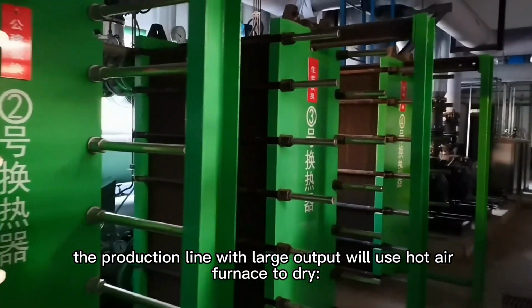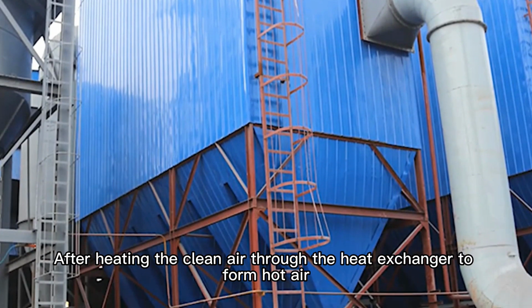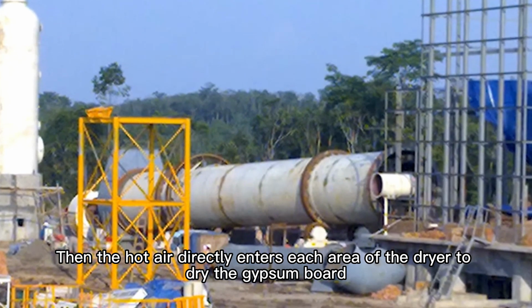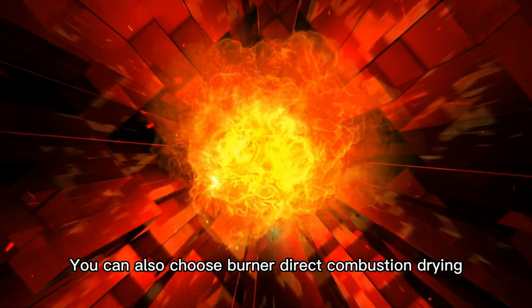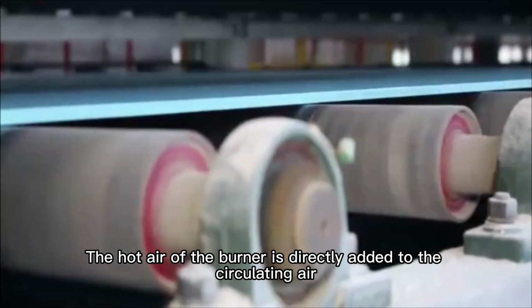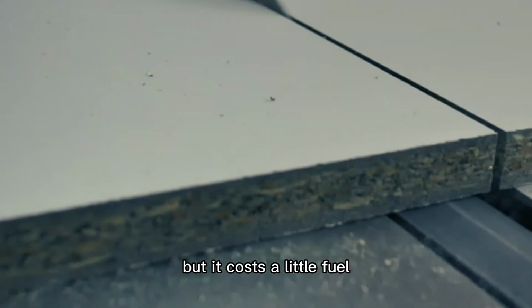At present, the production line with large output will use a hot air furnace to dry. After heating the clean air through the heat exchanger to form hot air, the hot air directly enters each area of the dryer to dry the gypsum board, which is clean and hygienic. You can also choose burner direct combustion drying. This is a new drying method. The hot air of the burner is directly added to the circulating air. The temperature is high, the efficiency is fast, and the product is good, but it costs a little more fuel.